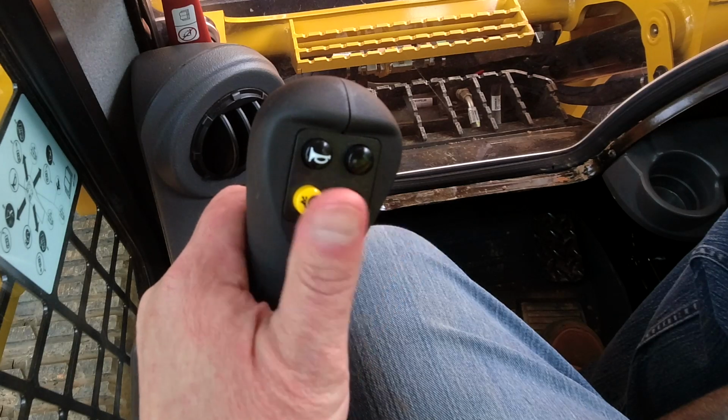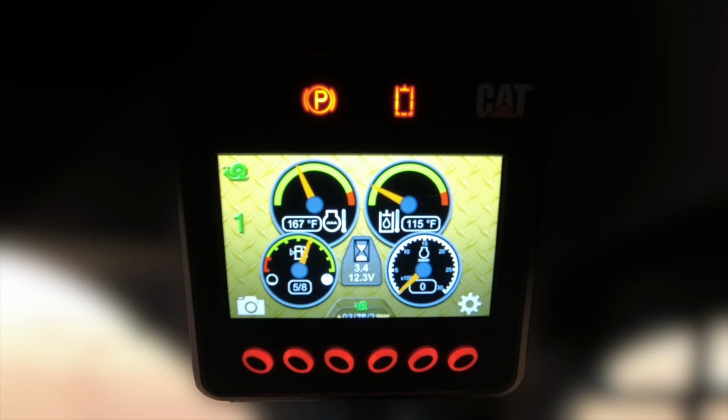When the creep activation button is depressed on the joystick, you will note that the upper left corner now shows a snail icon indicating the creeper setting, as well as the parameters that are able to be adjusted in the middle of the screen using the buttons below the arrow indicators. When the creep is turned to the off position, those disappear from the screen. Your adjustments range from 1 to 20.